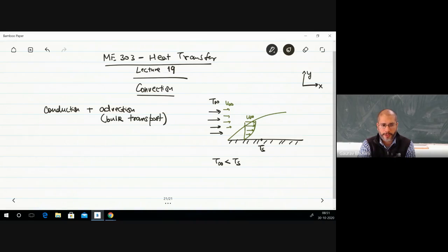So you have a processor which gets extremely hot when you are clocking it at a very high frequency, and this solid processor, semiconductor surface becomes extremely hot. You have a heat sink which is attached to it using a thermal paste. And that heat sink has nothing but lots of fins in it, and then you have a fan which blows air across the fins to cool the fins down, which ultimately cools down the processor surface as well. So that allows increased rate of heat flow from the processor, preventing that processor from becoming extremely hot, which can ultimately result in the failure of the material.